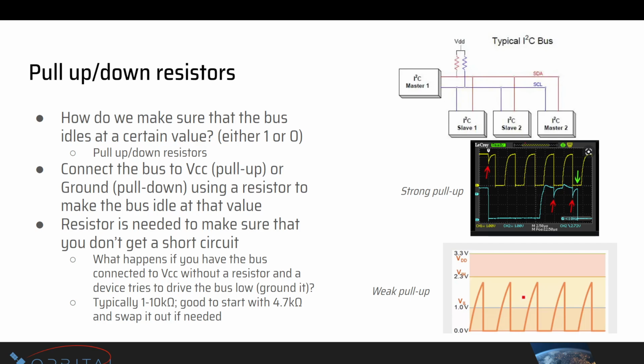Yeah. So when I say idle, I mean if none of your devices are trying to use this bus, like they don't have any data they're trying to send on there, so the bus isn't being used, it'll be held at some constant value, so that you don't have it floating and accidentally going to a zero or something and a device reads it as data. You just hold it at one.